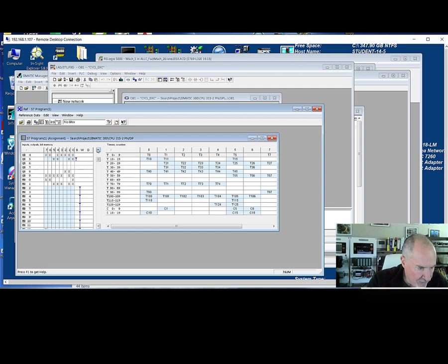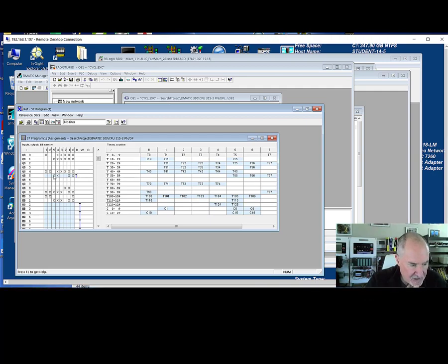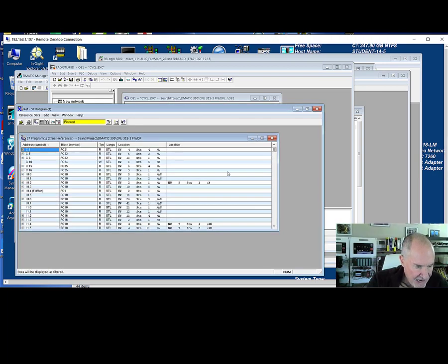And that might be important because, for instance, here, this output byte was addressed as an entire byte for one reason or another. I believe this was used in a fault in the program, but you can see also the bits were used here. So from here, you can see what was used, and we're just going to kind of pick something randomly here. So I'm going to go into the cross-reference, and now everything's in here in alphabetical order.